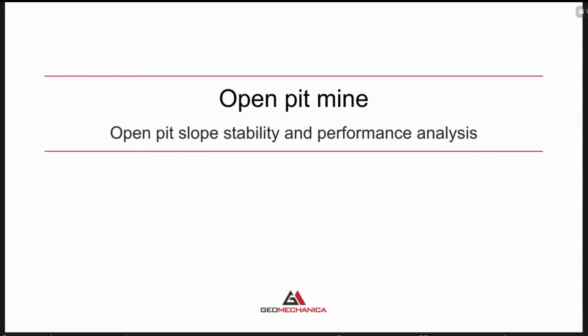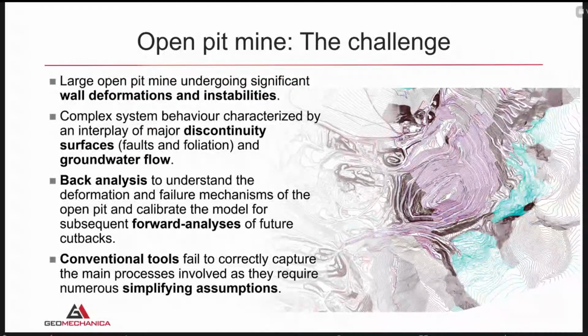So here, what was the challenge? The main challenges were that this was a large open pit mine that was undergoing significant wall deformations and instabilities. The system behavior was very complex and was characterized by an interplay of major discontinuity surfaces, including faults and foliation, as well as groundwater flow.